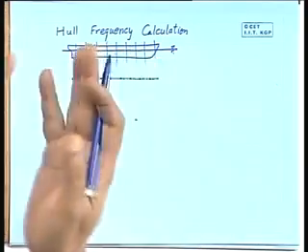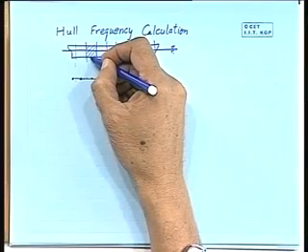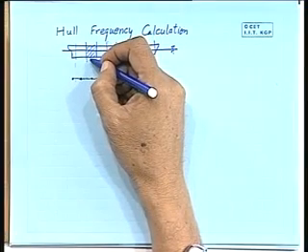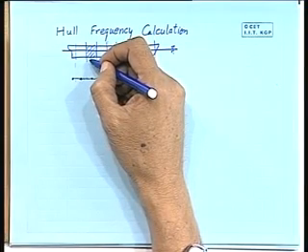To find out the rest of the properties, you require the shape of the vessel, right. So, the lines plan which has been done for the ship, now we are coming to the detailed calculation. The lines plan is now available, and from it I get a section shape here. So, I get the exact B, the exact D and the B by D ratio or whatever it is.